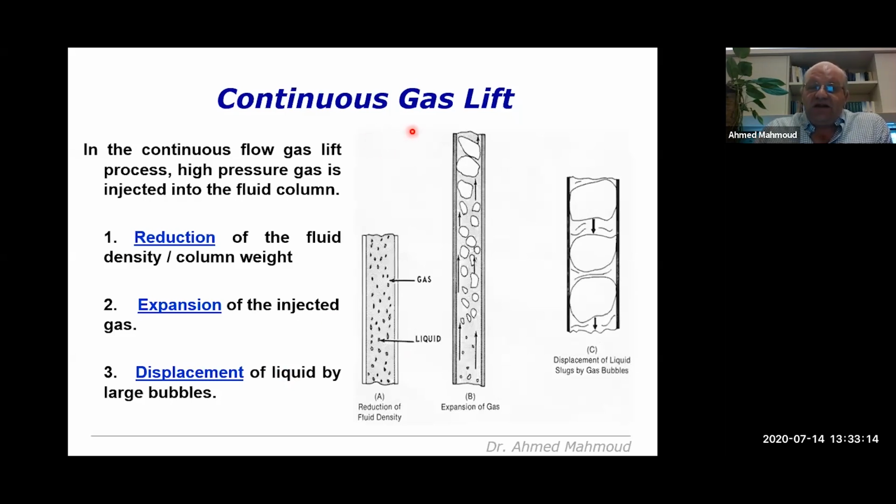So for the case of continuous gas lift, okay, the concept is based on three things: reduction, expansion, and displacement. First of all, it's the reduction of the fluid density and weight column. Initially, I inject gas, and this gas is dissolved inside the fluid, and then this gas starts to expand, and the gas bubbles start to commingle together, and they become bigger bubbles, and then they become even stronger and stronger, and they become like bigger bubbles that are now more powerful and can lift heavier fluids to surface, and they